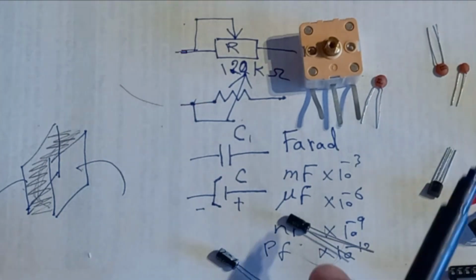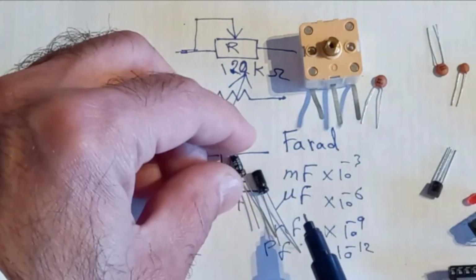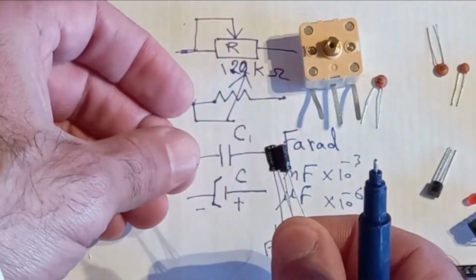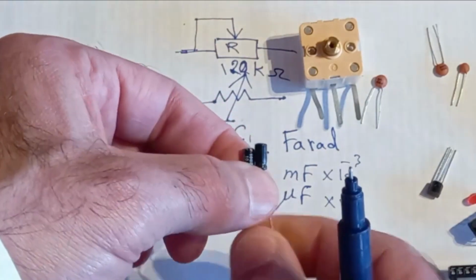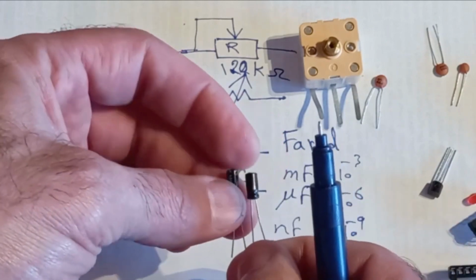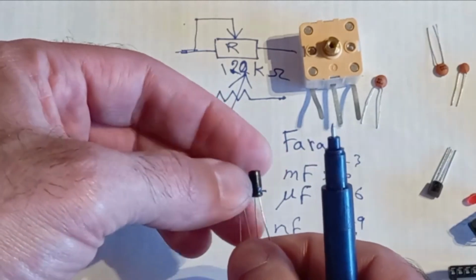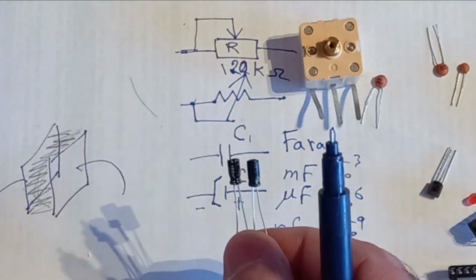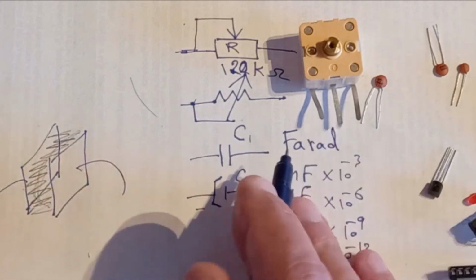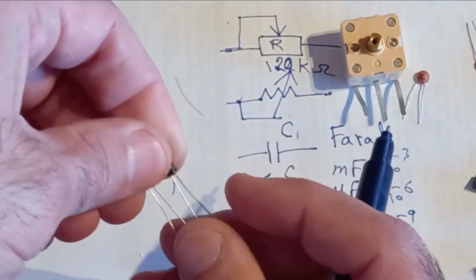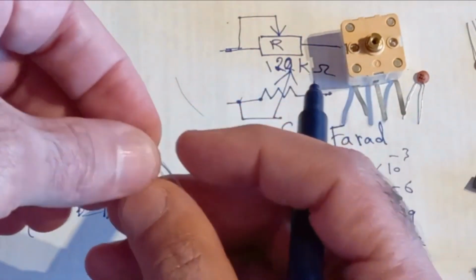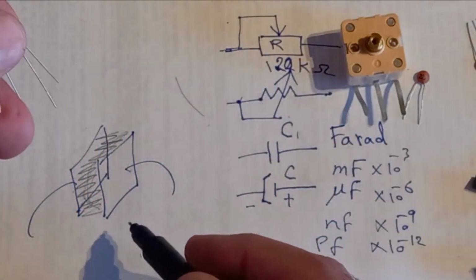In the case of electrolytic capacitors, the ones that have polarity and it matters which way you connect them, the dielectric is a chemical substance, electrochemical substance that, when you connect the capacitors the right way, starts basically electrolyzing, and it causes a chemical reaction in between the plates that causes the electrostatic field in between the plates, which is why it's dangerous if you connect them the wrong way around, because you can have the dielectric, in this case the chemical substance, react and cause explosion.